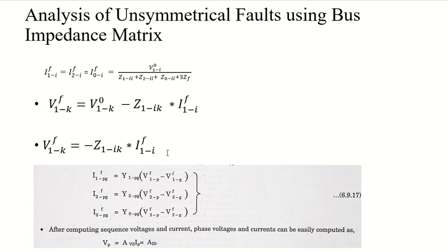And once you calculate the zero sequence, negative sequence, and positive sequence voltages, you will have all the post fault sequence voltages. No, you will not have the sequence current in the line yet; you will be finding the sequence current in the line, right? You can find the sequence current in the line based on the admittance. Remember what the admittance is? Admittance is basically the inverse of my impedance. So you can find the values of Y1, Y2, Y0, and you can calculate the current.